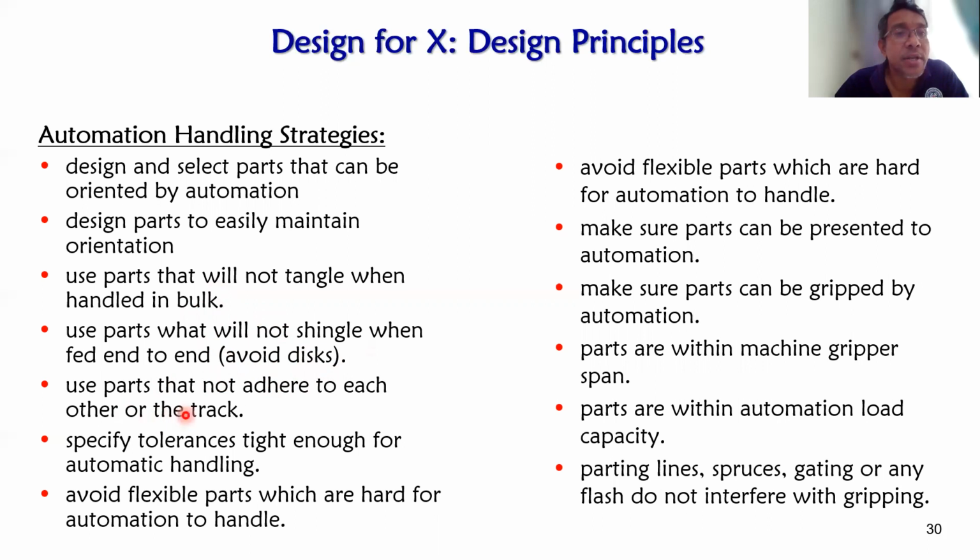So use parts that do not adhere to each other on the track. Specific tolerance tight enough, automatic handling, avoid flexible parts which are hard for automation. So there is the automation strategy.